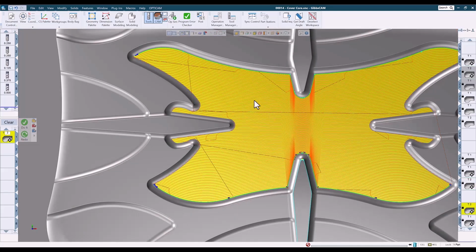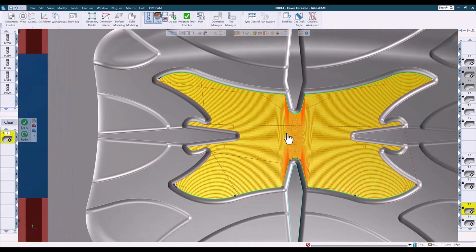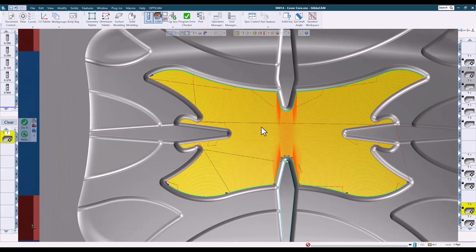Here's an advanced 3D in-curve flow, where the toolpath is morphing from the upper shape to the lower shape as it crosses the cut area. Now this is a very usable option and is getting close to what I would be looking for. But with this shape, as the drive curves change direction and head more toward the opposite drive curve, the toolpath gets really dense, which is less efficient and really not what I'm looking for. But this one only misses the constant step over by about 35 seconds in runtime. So it's still pretty efficient.